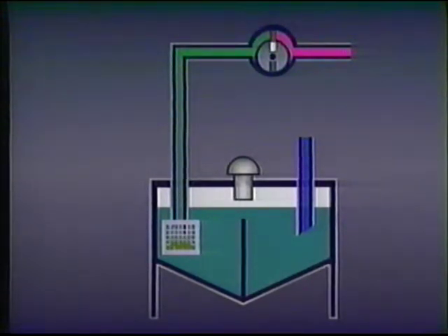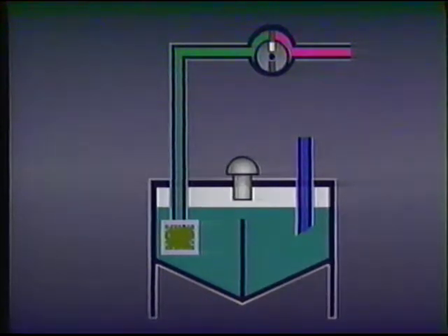However, since sump strainers are below fluid level, they are hard to clean, especially if the fluid is hot. They also have no indicator to tell when they're dirty, so they can easily get dirty enough to starve the pump and cause cavitation before anyone notices their condition. Finally, sump filters do not protect the system from the contaminants generated by the pump.